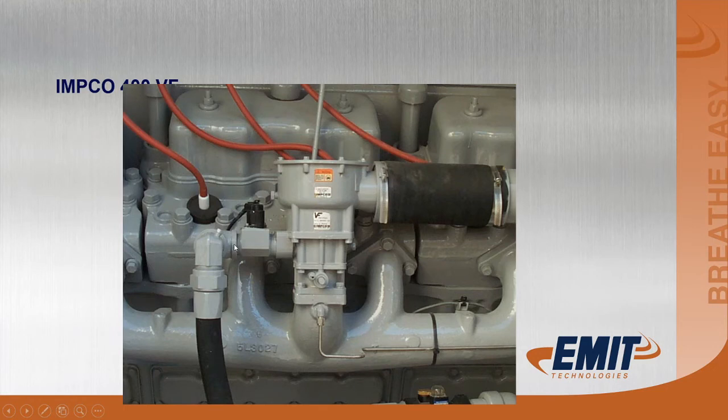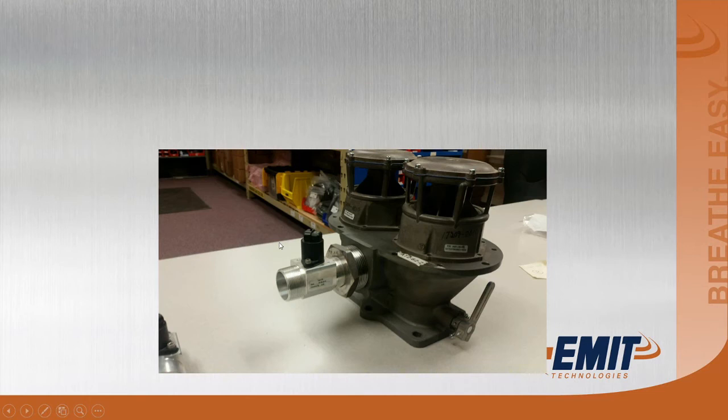Okay, here's a 1.25 inch on a 398 Caterpillar. You want that power valve as close to the mixer as possible. Don't get them down here too far away, or if you're not running hose and you're running piping. We see most commonly the problem with this is mounted too far from the mixer. The closer it is to the mixer, the better control you're going to have.